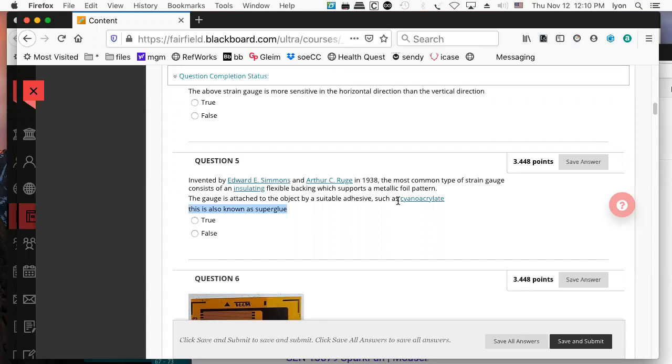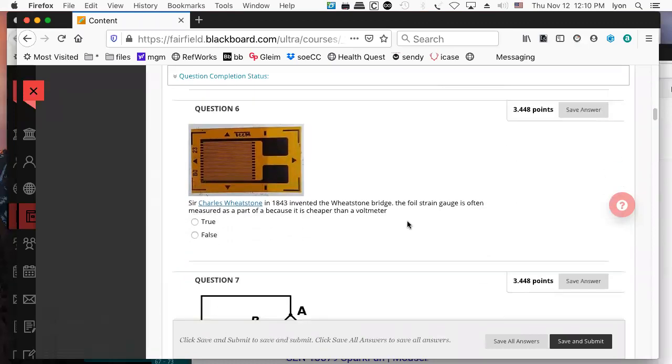So what do you do? Well, you take your little strain gauges and you use a little super glue and you stick them onto the airframes and check to see if there are any cracks propagating or anything going on toward the yield strength of the material. Because if it starts to fail, somebody could have a bad day, put it that way. And you want to try and avoid that.